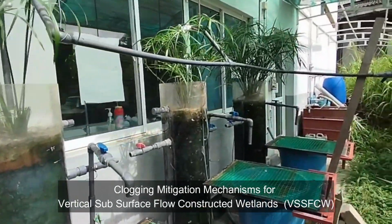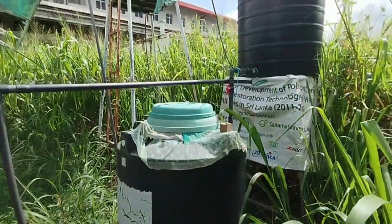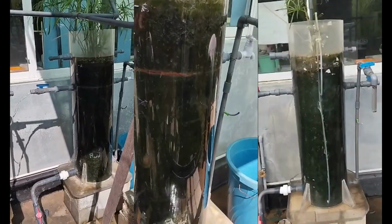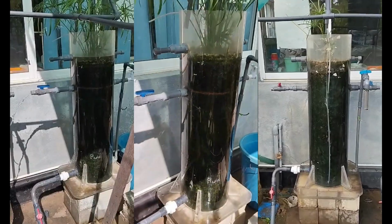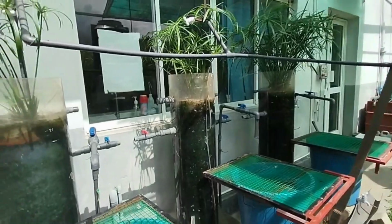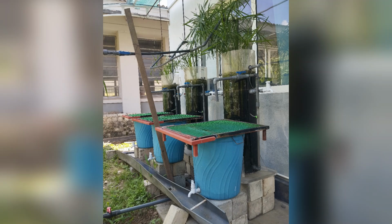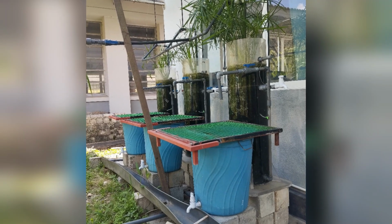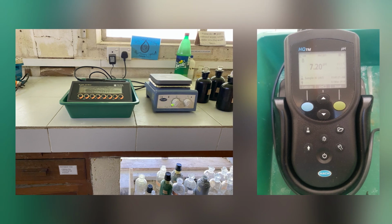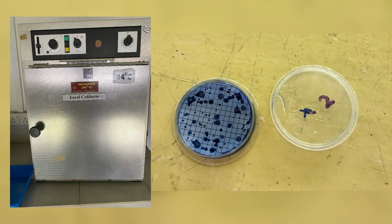Vertical subsurface flow constructed wetlands, VSSF-CWs, are effective for wastewater treatment, but often face clogging issues that can reduce efficiency. To address this, backwashing was introduced to mitigate clogging and enhance system performance. This research evaluated the impact of backwashing on VSSF-CWs by analyzing key water quality parameters, including pH, BOD5, COD, fecal coliforms, and total suspended solids, before and after the interventions.